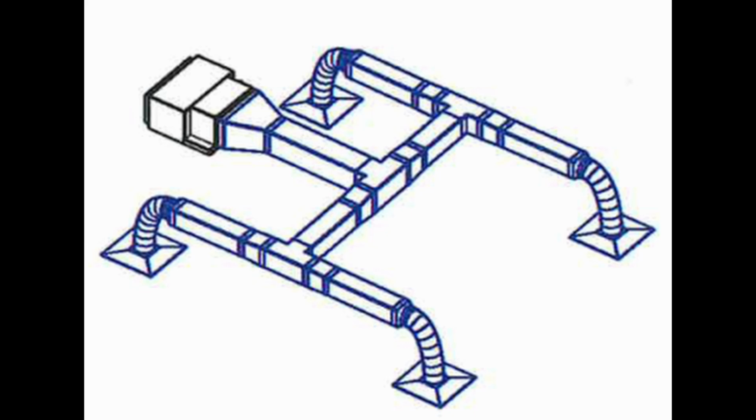If ceiling plans aren't provided, you may need to create reference planes or datum levels to assist in placing elements accurately. In this module, we also highlight an important principle. Even though Revit is intelligent, it's not magic. When creating MEP systems, you must follow certain steps carefully to ensure Revit can size and analyze the system properly. Examples include splitting duct or pipe elements before size changes, applying correct transitions, presetting duct conversions and loss coefficients. These allow Revit to generate the correct results based on your design assumptions.